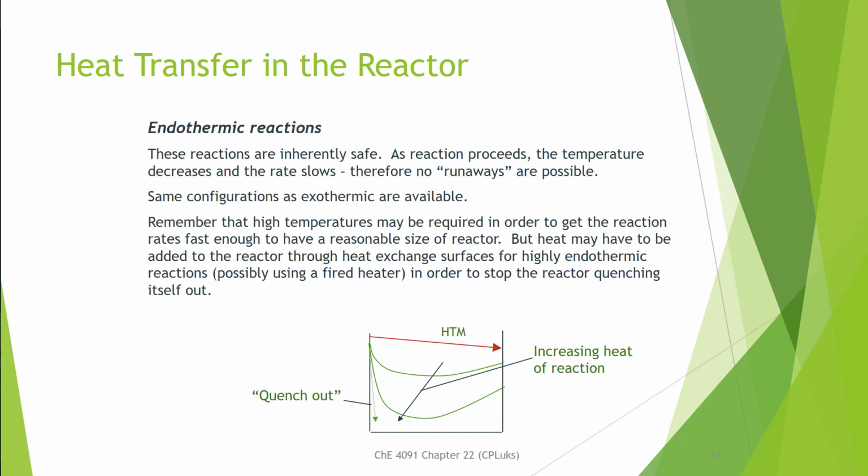And the final case that we want to consider is the endothermic reaction. Now, the good news is that these are safe. As the reaction proceeds, the temperature will decrease and it will slow the reaction, so you can't have a runaway. But you may need to inject heat so that the reaction will even proceed.